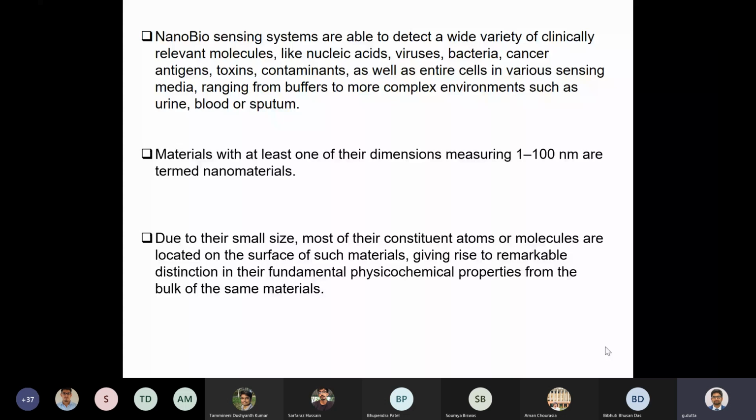I mentioned many times what signal and background are. Signal means what you are expecting from the biosensor. Background means the output without adding any sample. When you are not adding any sample, but still you get some output in the form of current or charge, that is background.